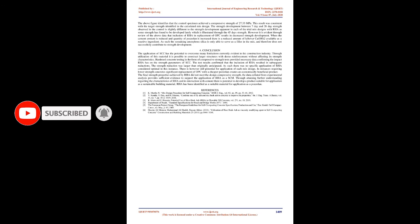There is, however, still potential for application of each mix design. In instances requiring lower strength concrete, significant replacement of OPC with a cheaper pozzolan creates an economically beneficial product. The final strength properties achieved with RHA did not meet the design compressive strength. The data collated from experimental analysis provides sufficient evidence to support the application of RHA as an SCM. Through attaining further understanding regarding the characteristics of RHA and its interaction with cement, there is potential to develop a product suitable for application as a sustainable building material. RHA has been identified as a suitable material for application as a pozzolan.